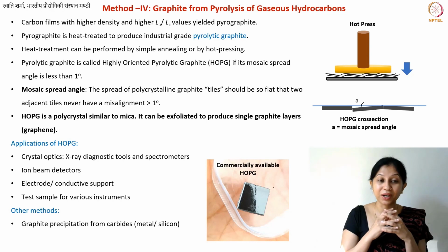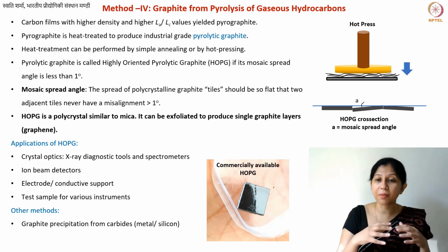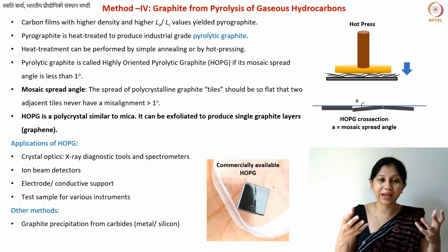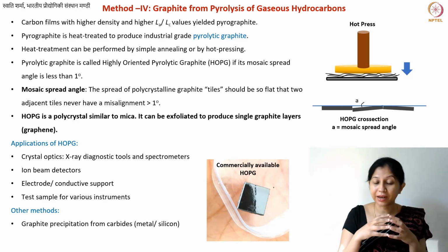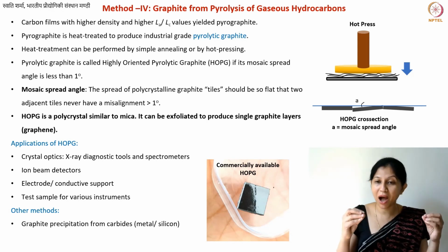is, when you're carbonizing a polymer or any organic material, which may be even mesophase pitch, for example, whenever you're carbonizing it, you can already add some metal nanoparticles into it. Or not nanoparticles, but even slightly larger particles, you can add the powders of metals.